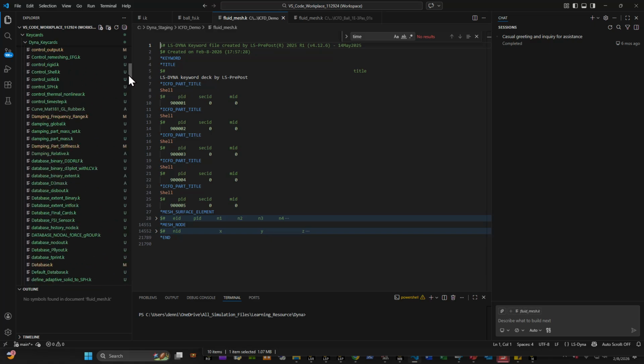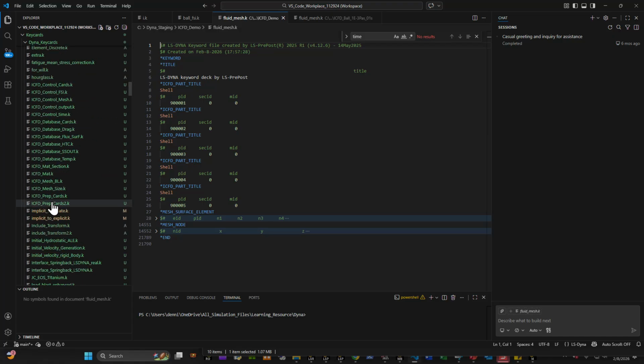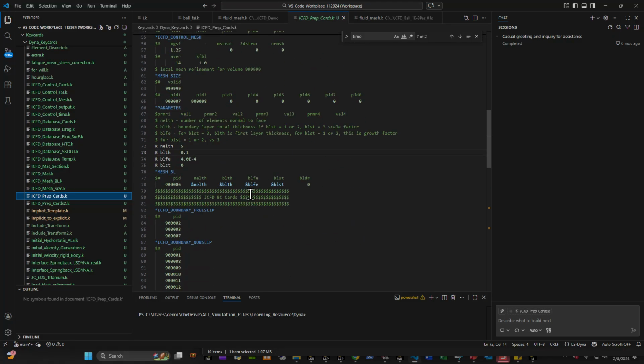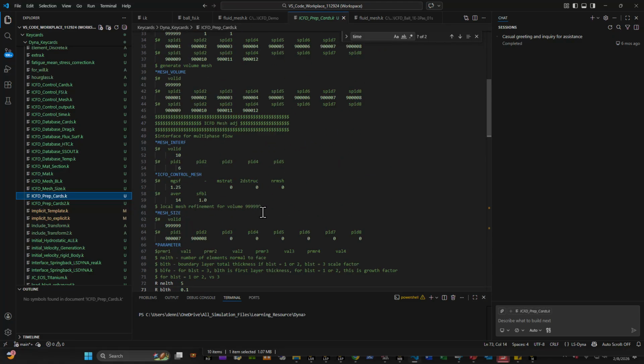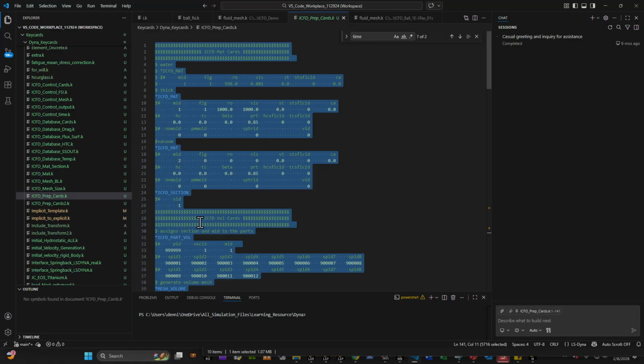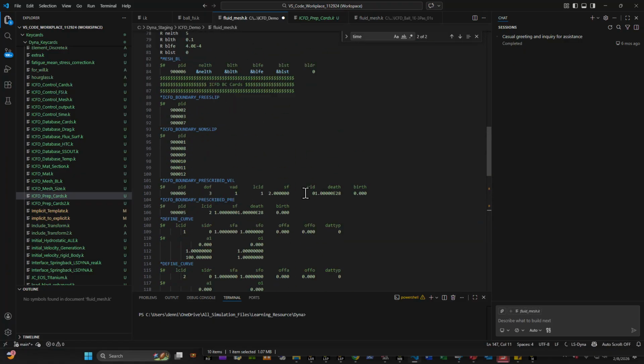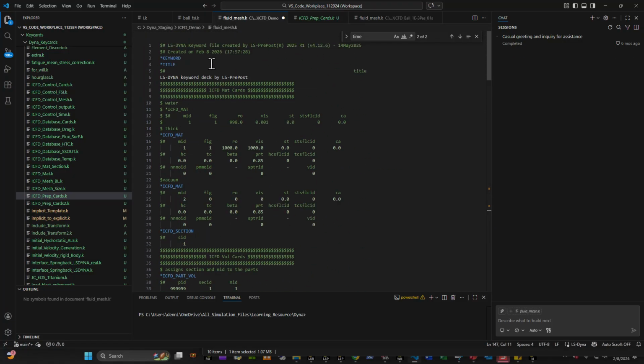or you can do what I'm about to do, which is I have a CFD setup template for basic problems. I mostly do CFD analysis in Dyna, mostly for FSI reasons, right? So the kind of thing I use is a keyword template that I can basically use and apply to everything, right? So I already have this prepared. Now I'll go over this as I do this, so that you can sort of see what I'm doing, okay? And I'll go over this one by one. And I already created sections for this.